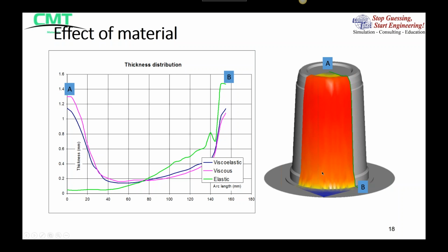This is often done during simulation: we take advantage of any periodicity or axis of symmetry so that we can minimize the amount of calculations that need to be done, and thereby get a faster solution, or a finer solution in a reasonable amount of time.